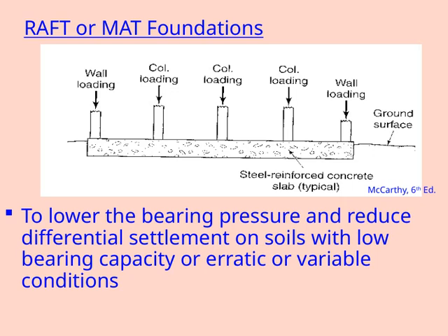These types of foundations are particularly useful when we're dealing with soils that have low bearing capacity or when the conditions are quite erratic or variable. The main goal here is to lower the bearing pressure exerted on the soil, which helps in preventing excessive settlement. By spreading the load over a larger area, raft or mat foundations reduce the risk of differential settlement, which can cause uneven settling and structural issues down the line. This approach is especially important in challenging soil conditions, ensuring stability and durability for the structure.